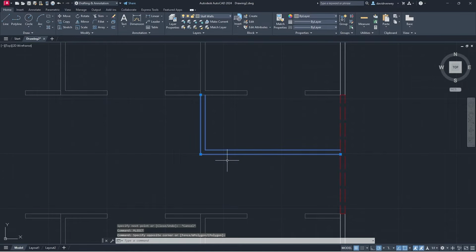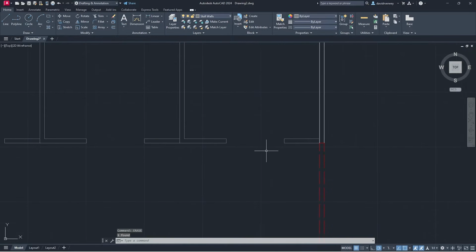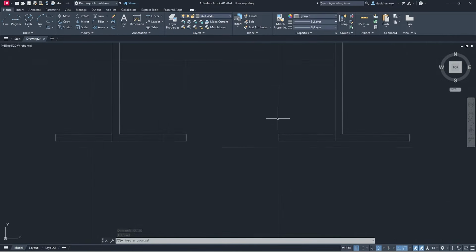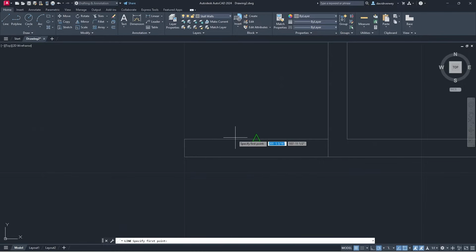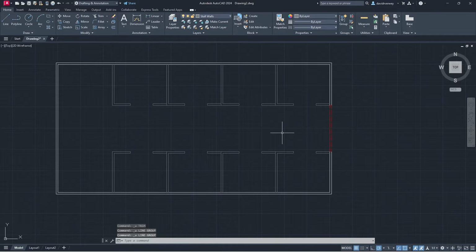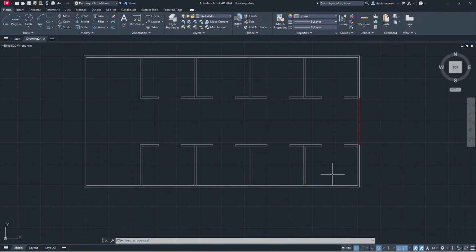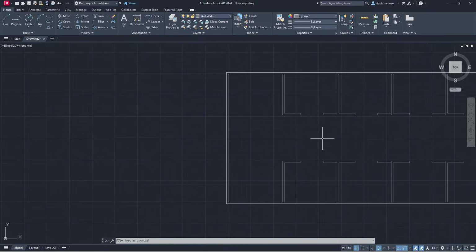One thing to note, which I didn't mention before, is that you can use the regular trim command if you put lines down. So what I mean by that is, if I put just lines down, let's say right here and right here, and I type in trim, then it'll trim the multi-line right there. So that's something that I did do. So just keep that in mind. So that's pretty much what I did, and then I mirrored and pulled, and then I mirrored this, and then I moved it down. So then we would have stalls, so it looks exactly the same on both sides.